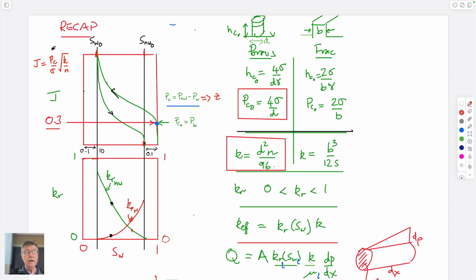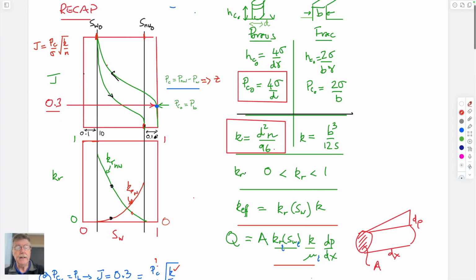So we can get a value of the entry pressure at 0 saturation, which says when we start to invade with another fluid. And this represents the behavior of a capillary barrier. This is the clay layer, which has the puddle of red NAPL sitting on top of it, because it can't get entry. It needs a much larger pressure than this to get entry. So that's the reality of that.